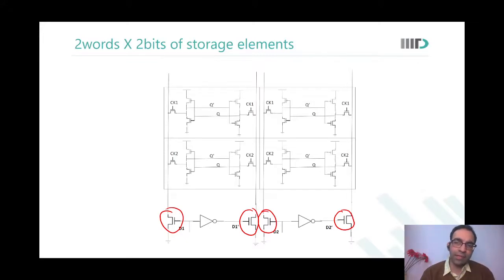Sir. Yes, Raghav. So you have mentioned the clocks as different, clock 1 and clock 2. So sir, the internal clock that we generate goes to our row decoder, and based upon my address bits, it gets connected to the word line. That is what decoding is, right?